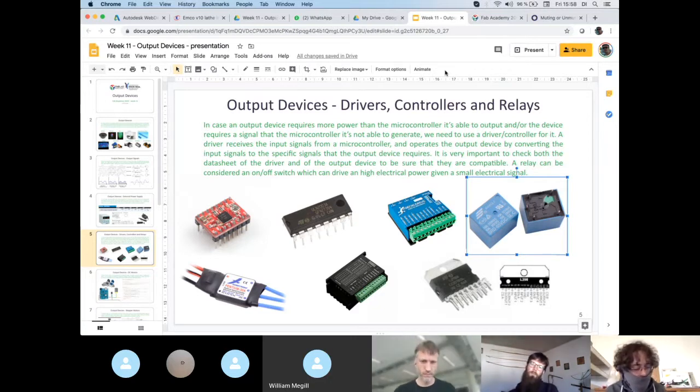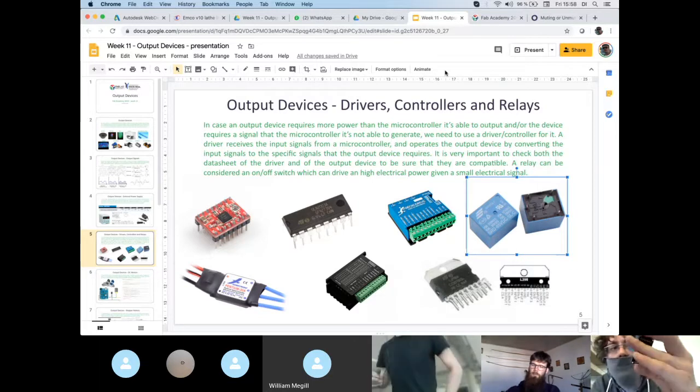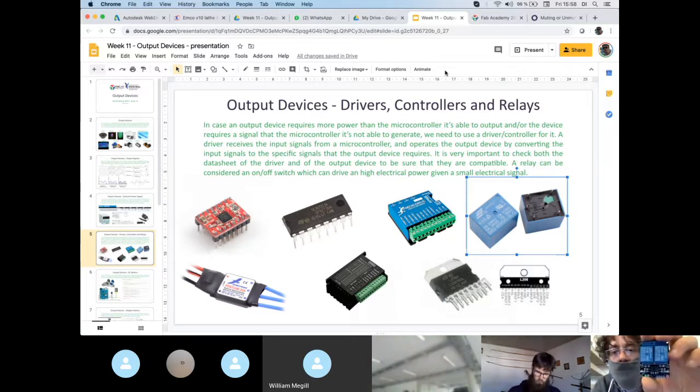In this case, for example, this board that I have here, you have to check your relays, guys. Some very simple and basic relays can be driven directly from the microcontroller, but some relays have the coil inside, and the coil needs current to flow to generate a magnetic field to switch the circuit, and this coil can take more current than the microcontroller can give you.